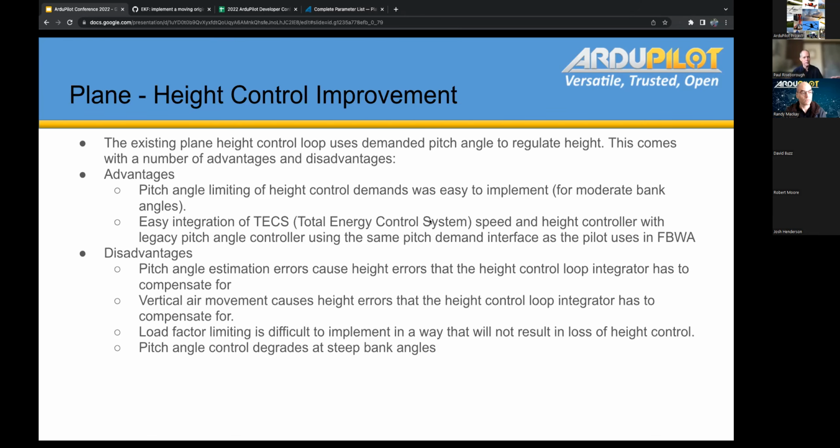You could leave it in a position hold or loiter mode, but it would drift with the error in the wind estimate and some other things. Yeah, it would drift, but it wasn't uncontrolled drift. In other words, there's a velocity error, but it's a constrained error. It's not that exponential acceleration and fly-away you get if you're flying pure inertial.